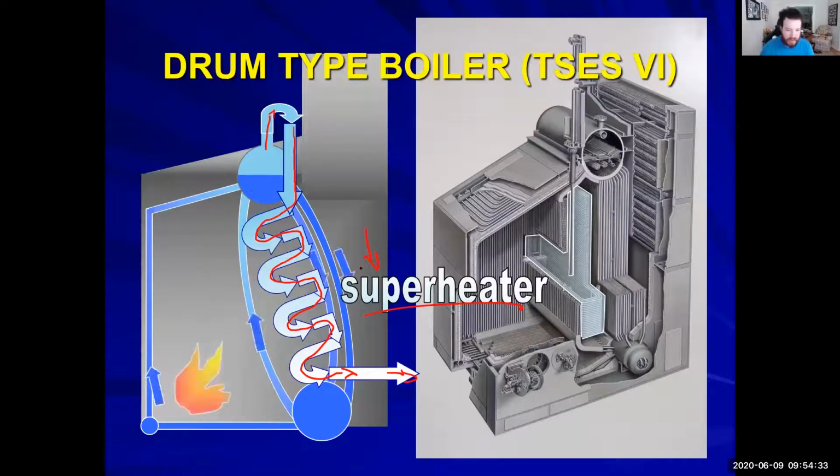And that is why these generating tubes exist. And there's only 2 of them right here. They're basically just protecting the superheater. If that superheater was exposed to pure flame, it would probably melt. So those tubes on this side are just there to give it that little bit of buffer that it needs.